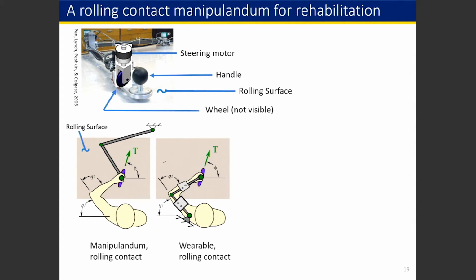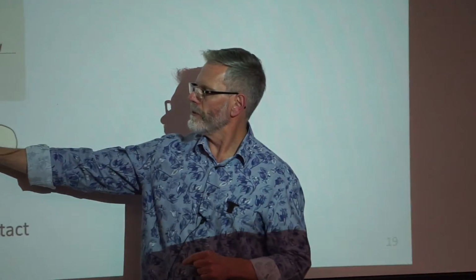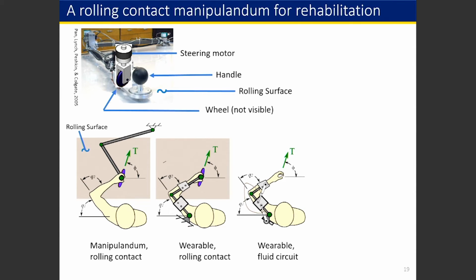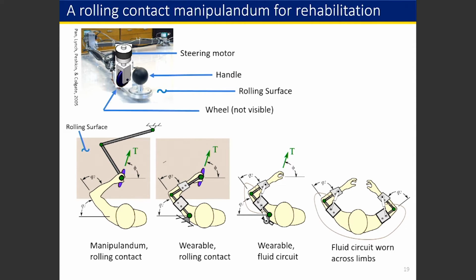We thought it might be quite interesting to talk about more than one degree of freedom, or a planar surface. One direction to do that would be to make the device wearable, remove that ground contact, and then even talk about constraining, not motorizing, the motion of more than one joint. You could constrain, for example, two elbows, and then you're able to drive an impaired elbow with a less impaired elbow and assist yourself, so it becomes self-assist.